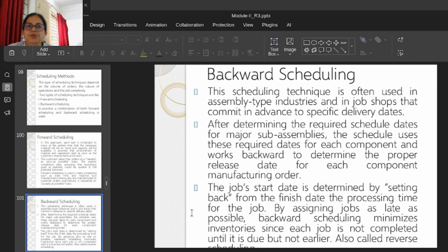No need to keep it in stock, because when we know the order, we calculate the exact time we need for the production process. Then we start at the right time and end with the same date as the delivery, so that we can deliver the product to the customer. So no need of keeping that in stock. This is called backward scheduling or backward calculation. To mainly avoid the inventory cost, we go for backward scheduling.